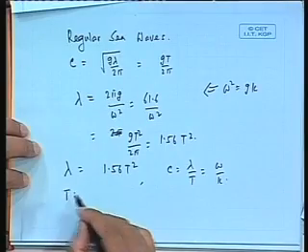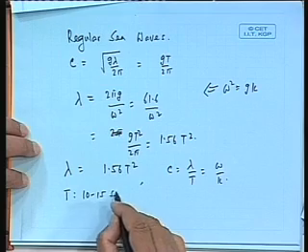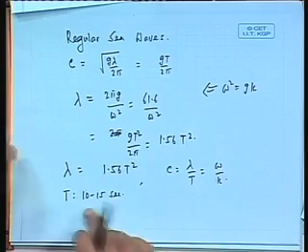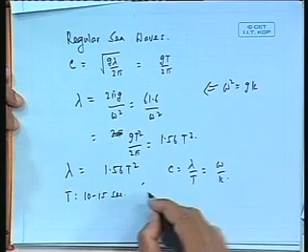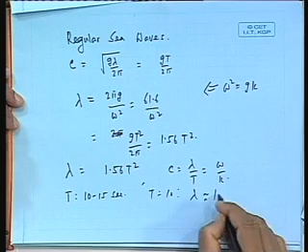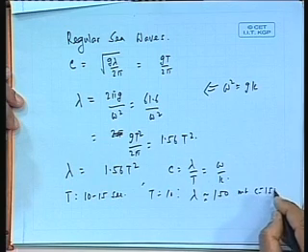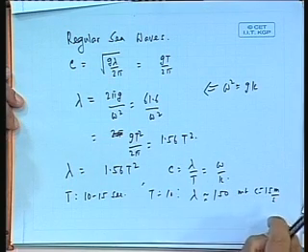Now, typical ocean waves, what we call everyday waves, T typically may vary between say 10 to 15 seconds. In fact, one can say even lower, maybe 8 to 15 seconds or so. Let us take 10 seconds to be a typical example. This is what is called in our terminology an everyday wave. Some people in offshore structures call it the most frequently occurring kind of wave. T equal to 10 will give you lambda approximately equal to 150 meter, and c will become equal to 15 meter per second, which is about 30 knots, quite high. This is actually an everyday wave.